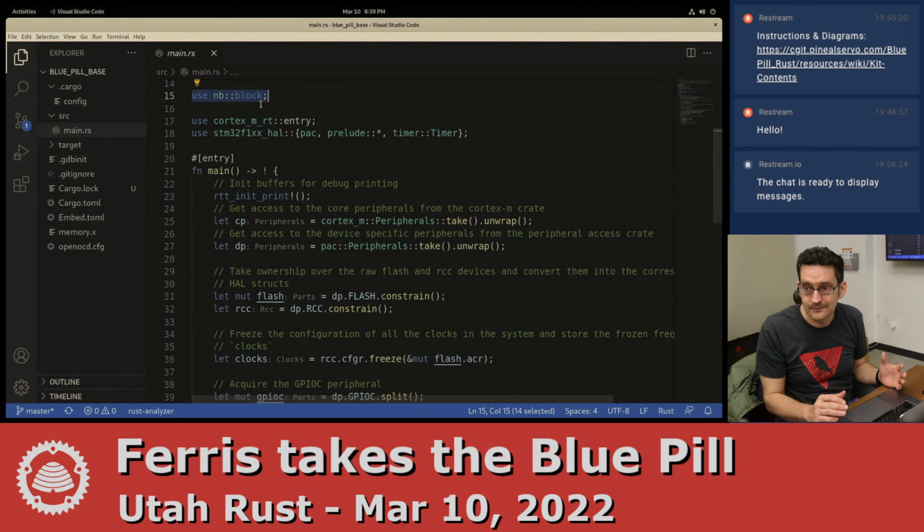So before it was a cargo build release, right? Yeah. Okay. So you saw there were some fancy progress bar things. That was cargo embed flashing your program onto the flash memory inside the microcontroller. First it was erasing the flash, then it was loading the new program in, and then we launched it. It set up the RTT connection, and these are the print statements that we had in our code.